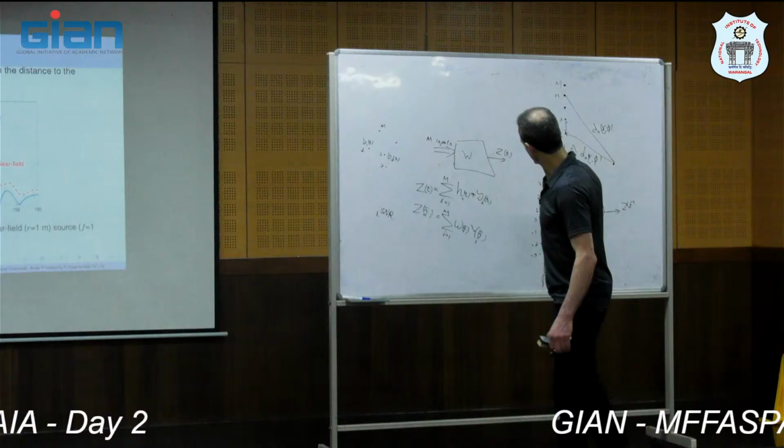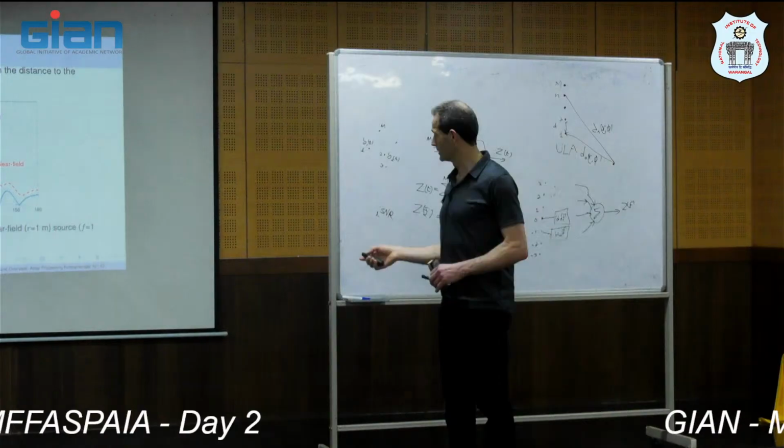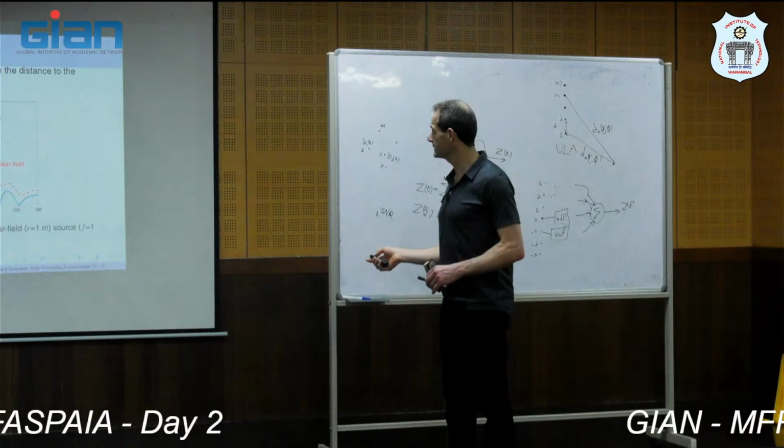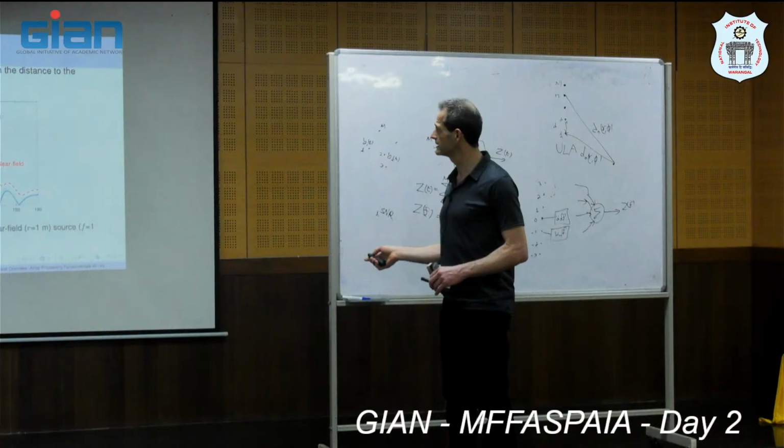But for the near field, suppose that we put the source 1 meter away from the array on a circle, because we take 90 degrees. We just want to see the variation versus phi, the horizontal direction. So you see that the near field directivity pattern goes like this. And of course, we can also normalize it to 1. It doesn't really matter, because what we care about is the differences between different directions.